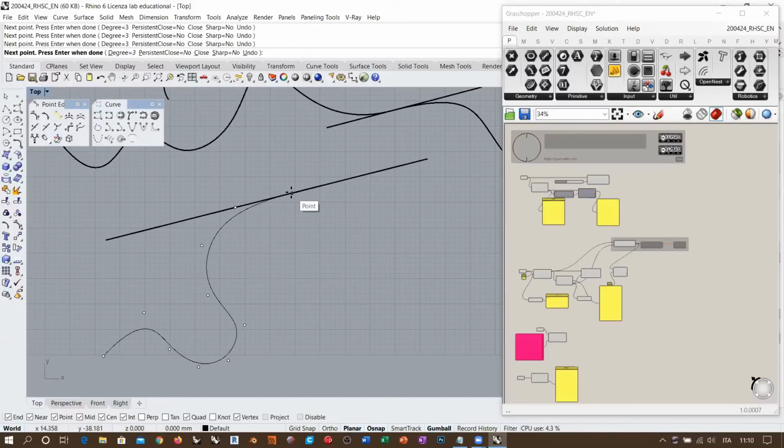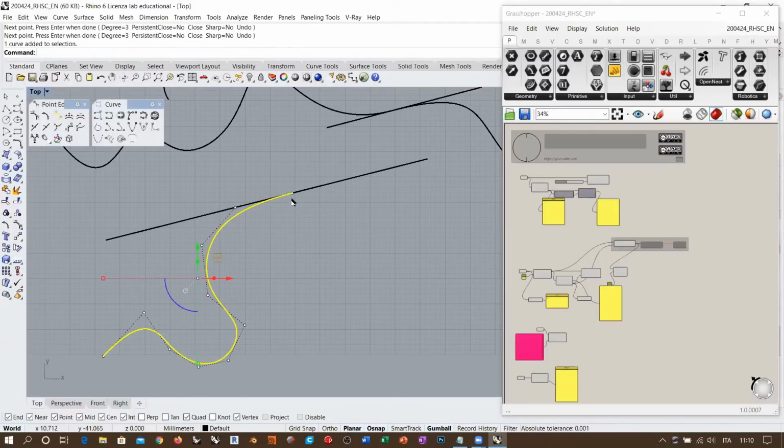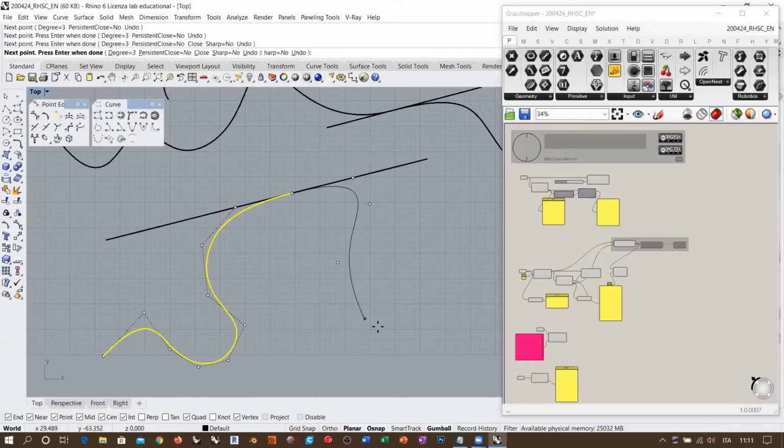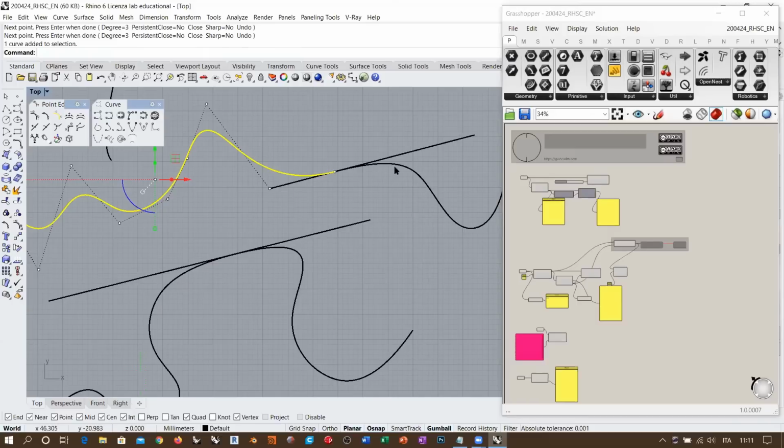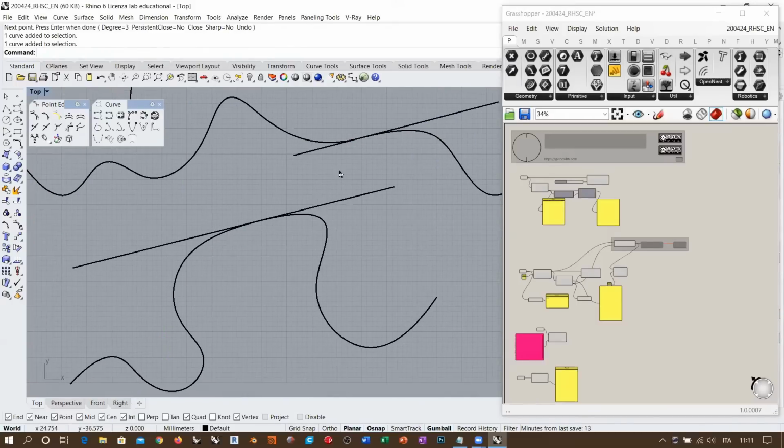Okay, so if I end the curve here, you see that this is the shape that I get, and my curve ends in this point with this tangent. Now, what if I start a new control point curve, starting from this point, and I want it to be tangent to the same line? It means that I have to place a second control point along this line, and then I can move away and do whatever I want. Now, if we consider this as we did in this scheme, we are reproducing exactly the same situation.